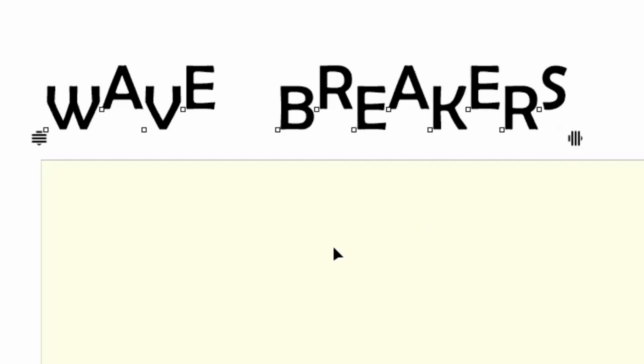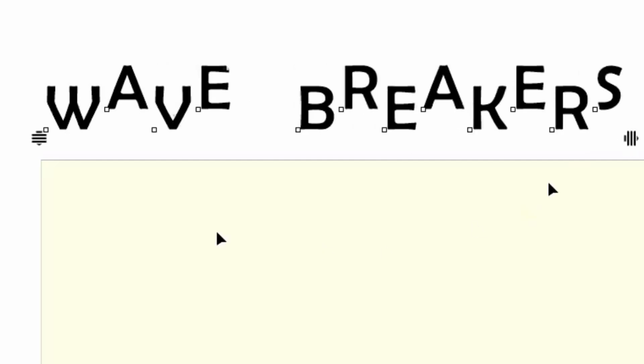And let's say that I want more space between the words. Well, that's what that same tool does. I just hold down my Shift key, and now I can change the space between the words. Okay, if I release my Shift key, now it changes the space between all the characters. So that's like inter-character spacing, if you will.